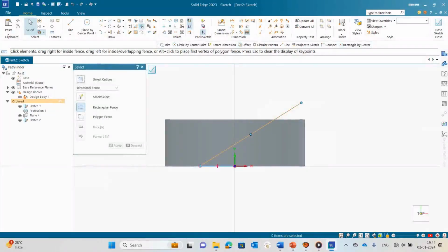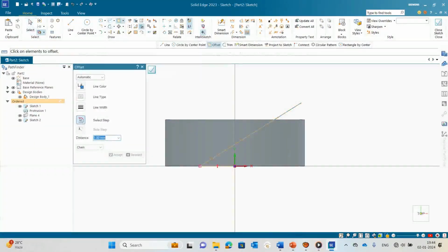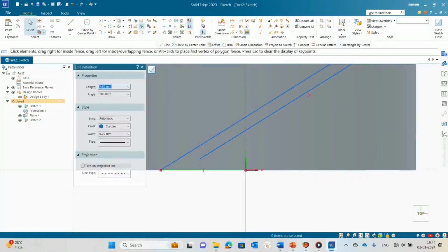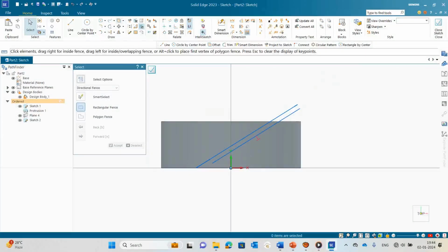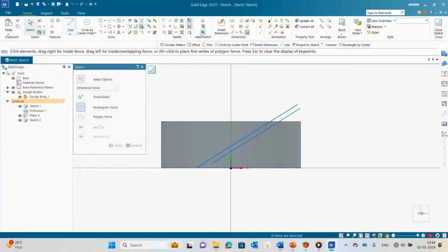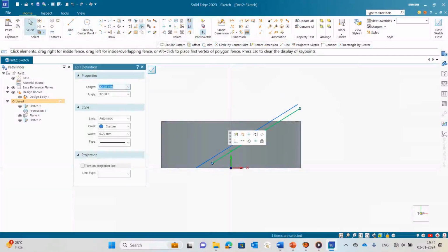So from here we should have the 1 mm thickness, so for that I am using the offset method, so it will give exactly the proper 1 mm. Okay, accept it. Then direction, okay, fine. Now I will trim this part also. Otherwise I will increase this length to 25. Oh, it is increasing in the opposite way, so it's fine, no issues.